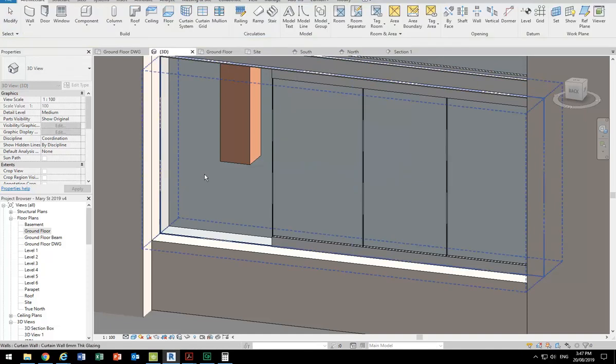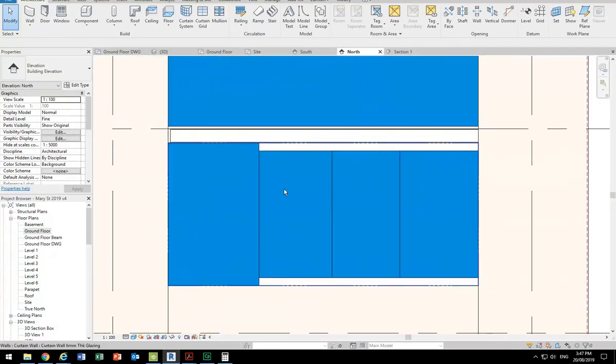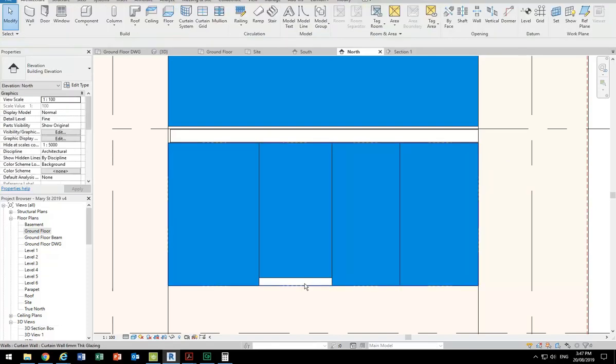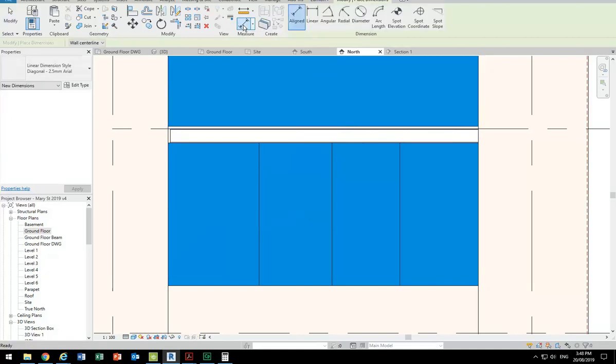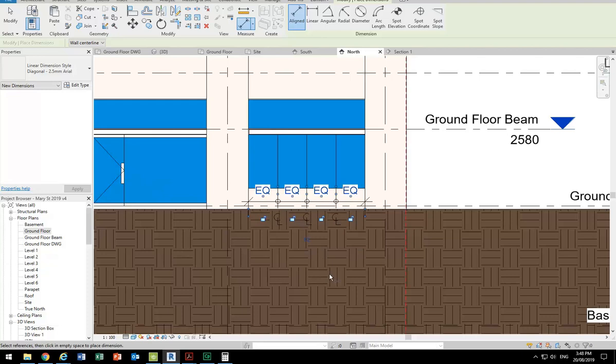So I might just finish up showing you how to get even grid spacings. So would you have an idea if you've got curtain grids like this? They're just grid lines. Maybe I'll take the mullions off just so it's easier for you to see the grids. So I've just got grids in that curtain wall. How would you make those grids even? If you want to make all those grid spacings exactly the same, you could sit there and measure it, so you could select them and measure the whole thing and then type in the measurements, but you don't have to. If you draw a dimension, so here you've got the dimension tool, a line dimension, go from one side to a grid, to a grid, to a grid, to the other side, place the dimension to one side, and then use the equals option. Yep.